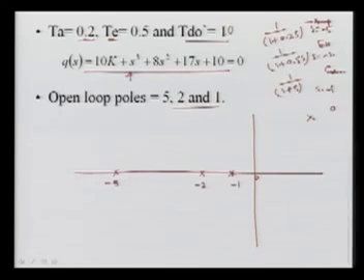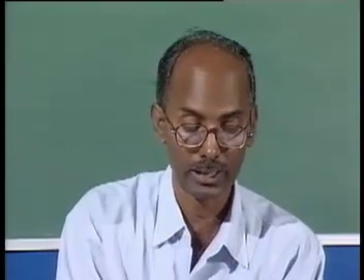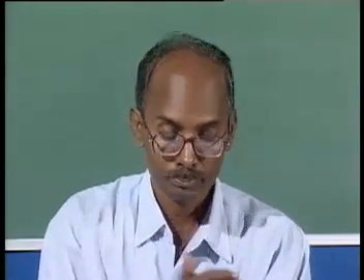Now there are various rules for the root locus and the movement of the roots. When k is 0, we get the open loop poles. So when k is 0 we start at this point, here also k is equal to 0, and at this value also k is equal to 0. But we want to change k from 0 to infinity, and then we will see how they change. Once k is 0, they lie here, and that is your open loop.